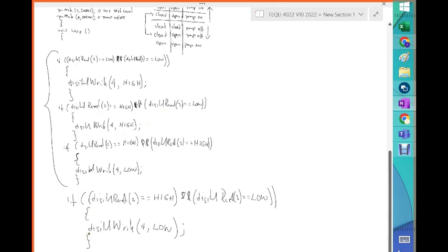See, because it's the same conditions. You know what I'm saying? They will fight each other. That's a bad design. This is bad code. Because you turn the pump on with this instruction here, but since I have the same conditions on this line here, I turn it off. I send a signal to turn the pump off. That's bad. Bad design.